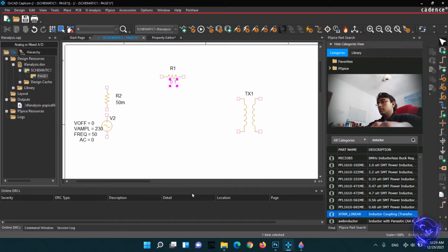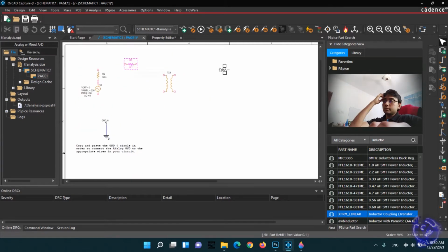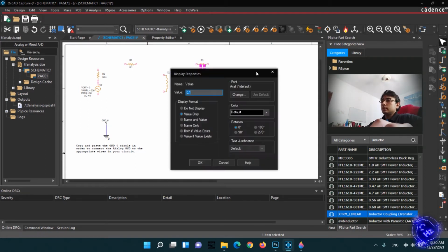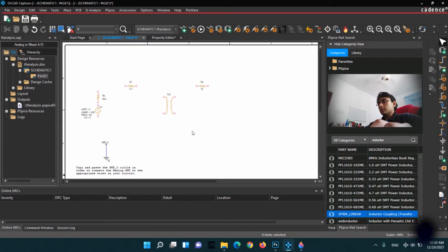And for my secondary winding resistance, I need to set some winding resistance values because this transformer is an ideal one. So my secondary winding resistance, I set it as 10 ohms. Why did I select those values like that? Primary winding resistance is lower than secondary winding resistance because I would like to build a step-up transformer. For a step-up transformer, I need more windings on my secondary. Because of that, I might get much higher resistance in my secondary winding. So, in tally with some practical values, I put those things.